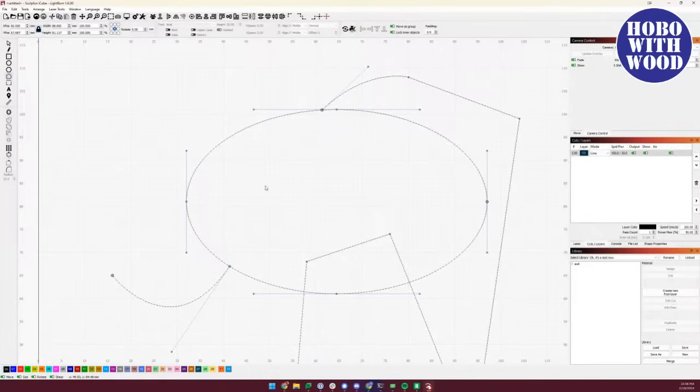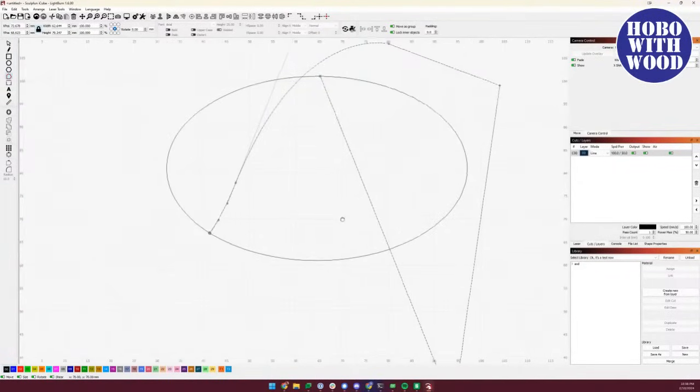If you hover over this, basically what it does is it finds the nearest intersection, like here and here, and it will trim between that. Or more likely, you're probably wanting to trim something that's outside of the shape. You can do that. The thing he was talking about in Vectric is there's basically a scissor tool, and you just click and drag over the things that you don't want, and then it gets rid of them. We've talked about it. We just haven't gotten there yet. But you can trim stuff out like that. You can also hit E to extend, and it does the opposite. It goes until the next intersection that it finds, and then it will add that on. It's just hover over the thing you don't want, hit T, and it goes away.